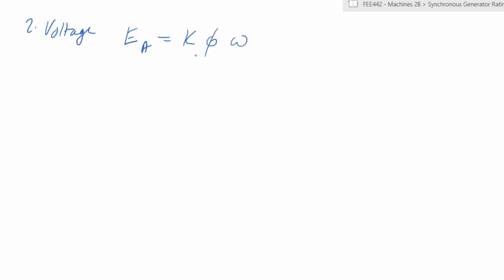So these three are the factors that affect the amount of voltage that you can supply. Now, the voltage is generated in relation to I_F, which is the field current. This is what we had already talked about in previous lectures, that the voltage is controlled by the field current that is supplied to the generator.